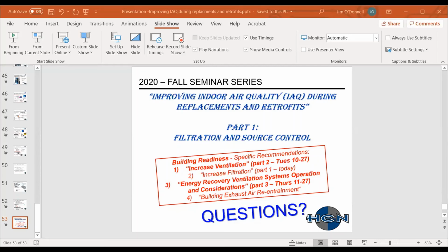As the air entered this device, the first plate would charge the ion negatively, and then downstream you would have a second plate with the opposite charge, and that second plate would be the one to capture the particles. So I think the question is referring to that type of device